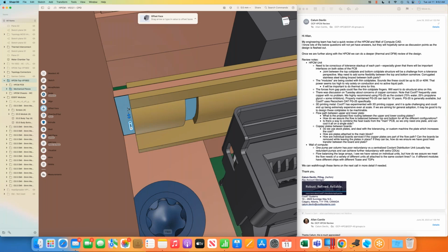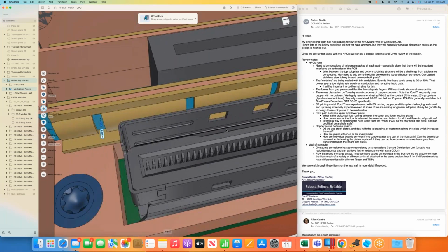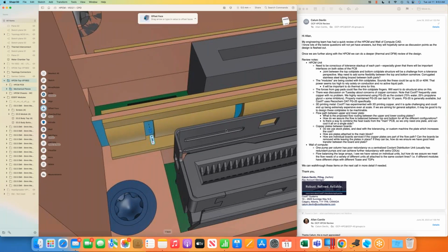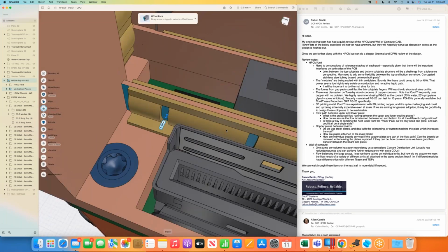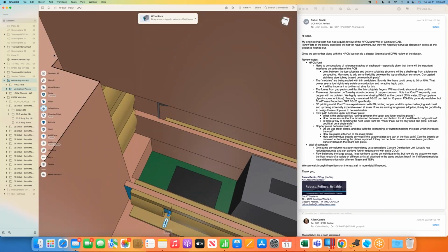Yeah, I was trying to get as much area as possible to bolt this, and that was the reason for putting gap pad behind this spring-loaded connector here, so you get a good thermal mate from this to the copper, which is then attached to where the water is flowing directly underneath this. And likewise, in the walls, the water is literally flowing directly up and down the walls, right behind these.